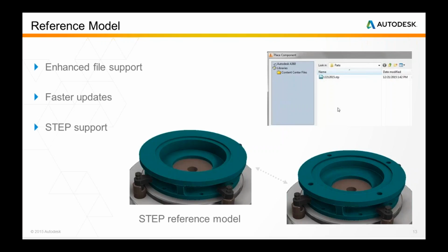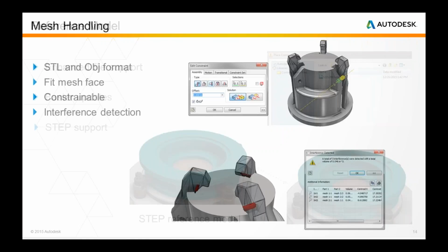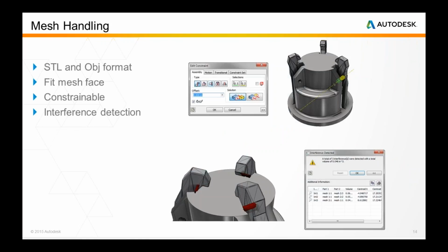We transfer those types of files, and then obviously you protect a little bit of your design information as well. If you want to send to a customer or a supplier, you convert it to one of these generic file types, and then you don't have to pass along the feature data, which is really what you're trying to protect. Obviously, you always run the risk of them reverse engineering your files, but that's one of the common tools there, the STEP file.